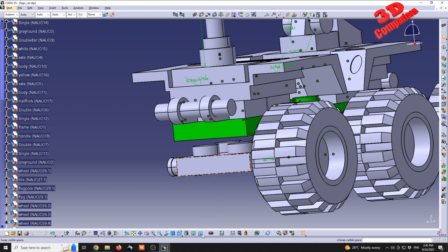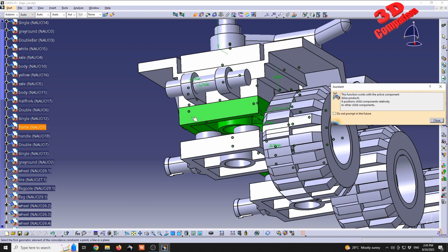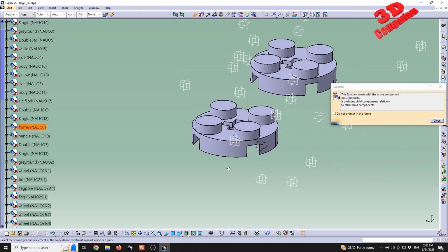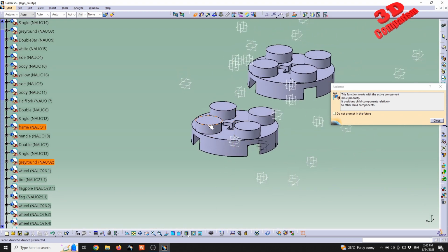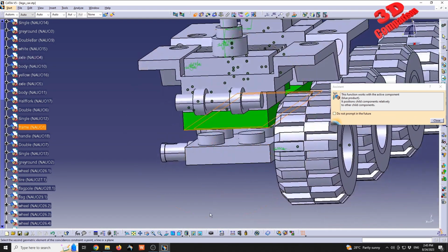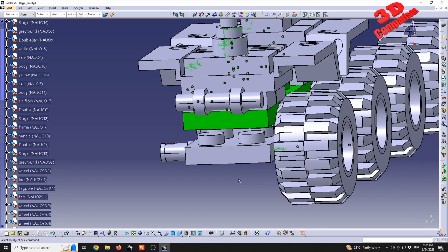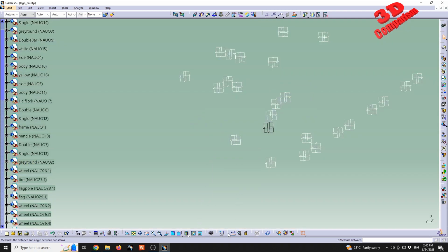So to do that, I'm gonna add a coincidence. We can also go with the contact constraint, so this will be the same just as coincidence if they are already in the same plane. So contact will keep that 0 offset. So we have that top part over there, and we have this part. Okay, I see that that moved, so that's not within the proper location.